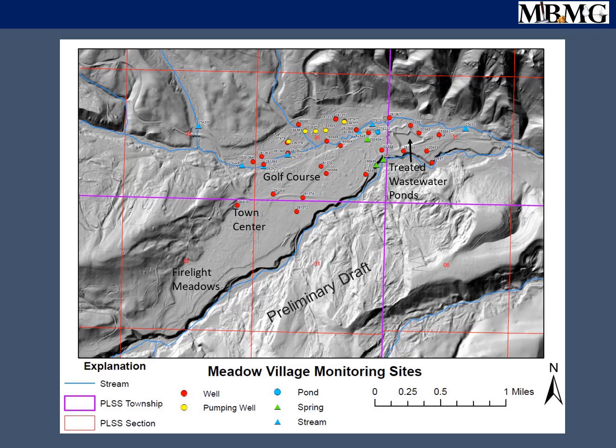And also, of course, the shaded relief here is from the LiDAR data for Big Sky, which is light detection and ranging elevation data that's very accurate. We had these red wells surveyed, and the survey data and the LiDAR are spot on. They're within a half an inch or less in terms of vertical elevation. So with that LiDAR data, you can really accurately position the stream in the model, and also all the wells and the data from those wells.